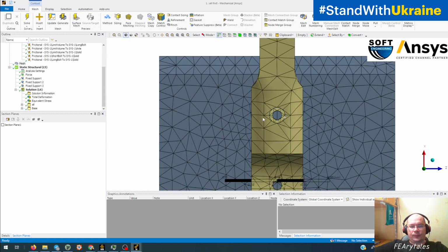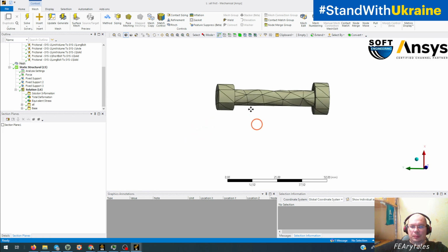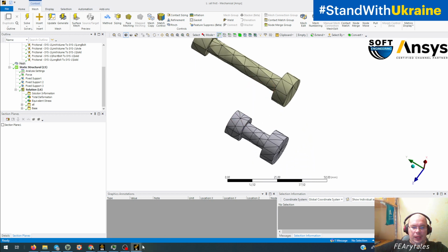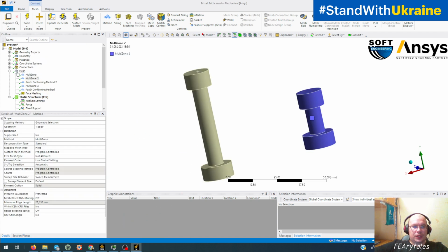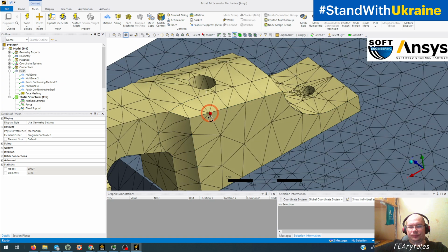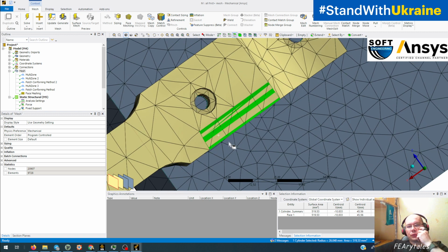Okay, change invert visibility. We see the mesh in automatic mode with those problems here, here, and so on. And we see how the mesh for this object looks here. So this is a much more adequate mesh. Invert visibility. This object is very difficult to mesh with only quadrilateral elements, only with brick elements.